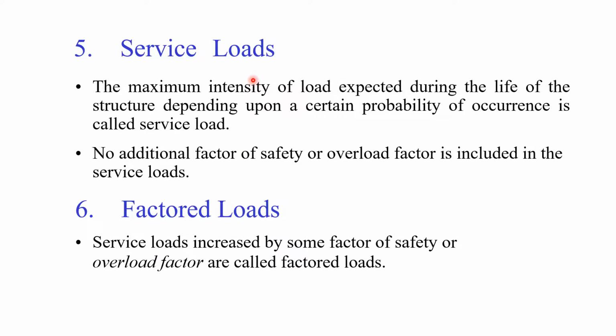Service loads. The simple definition of service loads: all the loads which act on the building throughout its life without any factor are called service loads. It means the maximum intensity of load expected during the life of the structure, depending upon a certain probability of occurrence. Here, no additional factor of safety or overload factor is included in the service load.